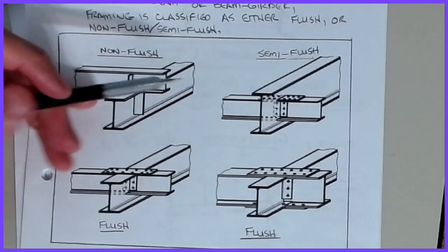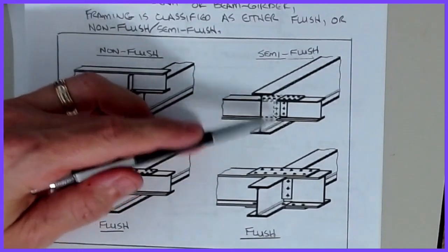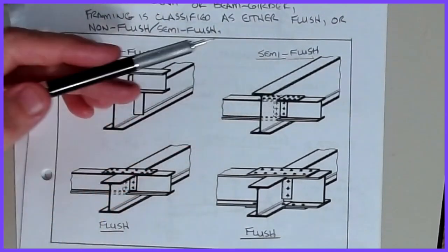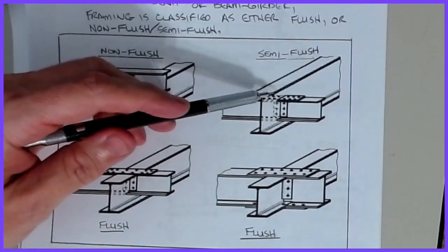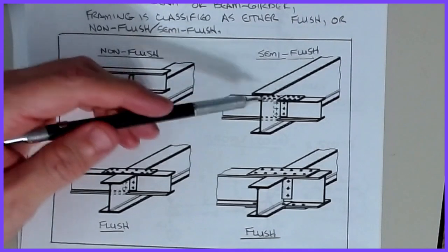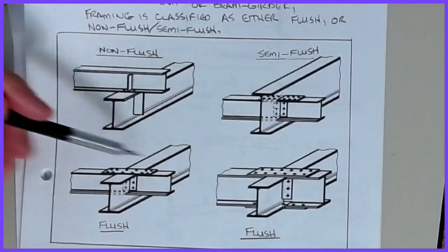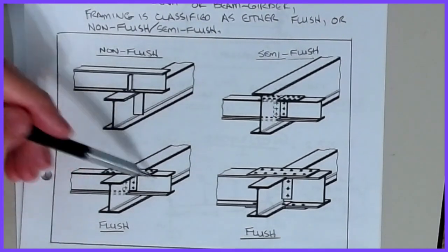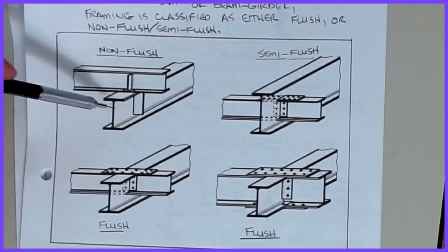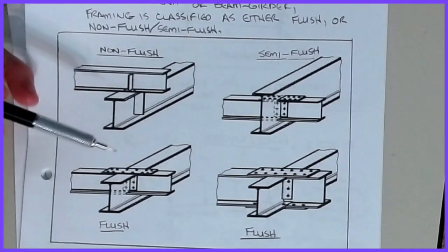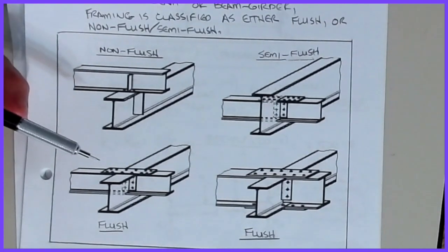Now there is something called a semi-flush, which is not flush on top or bottom. It's kind of held down. This one's unusual because in this case these are the beams, but it's the girder that carries the weight of the slab. Think about it: the slab spans between beam members, if there's another beam over here. So you're asking yourself, is the girder helping to hold the load? And that will dictate the changes in our particular areas.